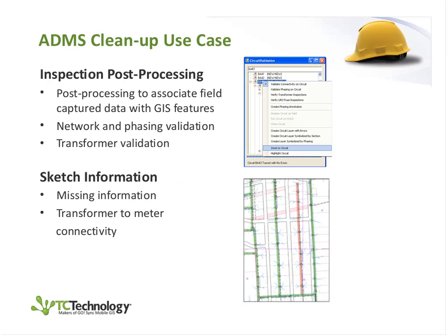And then finally, once that information is collected and you've put all of those data points into that system, you have to do some additional cleanup on the back end. You have to make sure that the information that you put down on a particular circuit line is propagated throughout the rest of that circuit. So if you've identified a tap point as B phase, and you've got a single phase line down to the service level, then you want to make sure that you propagate that change all the way through.